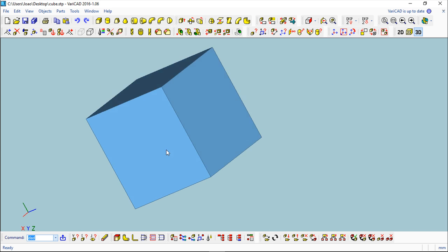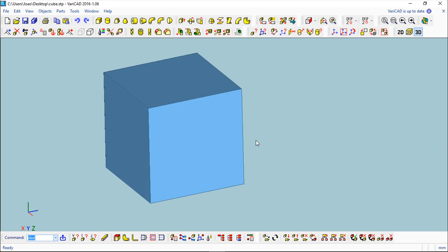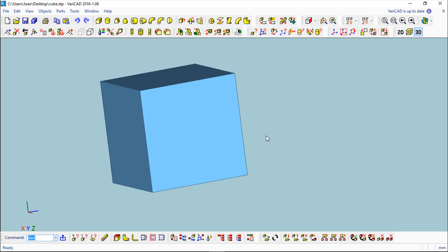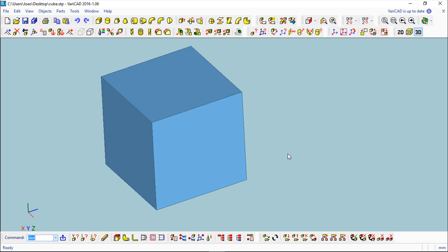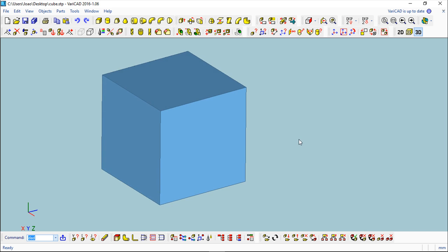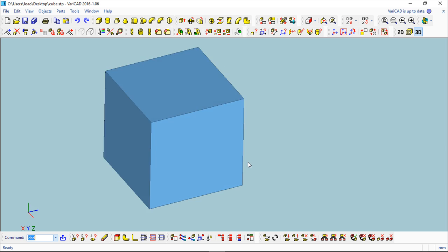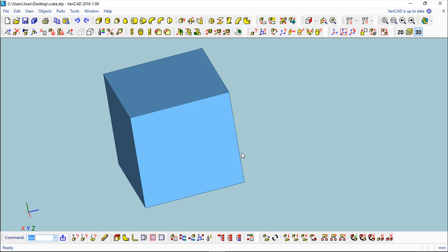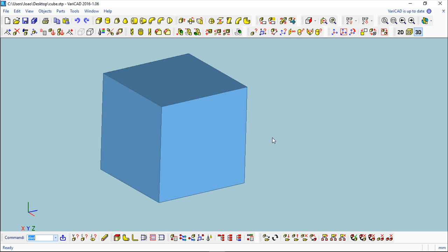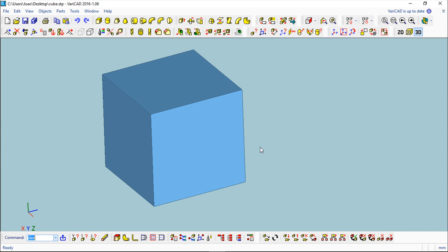But on the other side, if when you import the solid it is not perfectly closed, you cannot calculate volumes, masses, or moments of inertia for open geometry. So all this is to tell you that we have 4 types of solids or 4 types of representations. This is the first one. It is a closed surface or a closed shell, as I mentioned before.